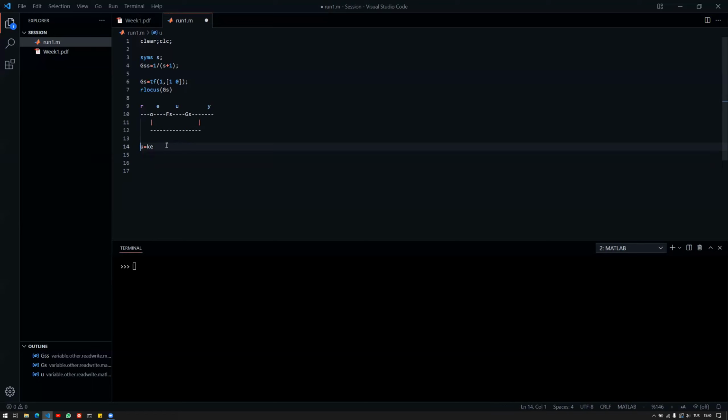Now, if we have such a feedback structure, then I need to work out what the closed loop transfer function looks like, because before I used a controller, I had just the system, the plant on its own. And this plant has a certain characteristic or behavior to it. But now I want to change that behavior in some sense so that I achieve my goal. This means that if I use a controller and have a feedback structure like this, the plant is not the system anymore. The system that I'm looking at is the feedback structure. So what is the transfer function of the closed loop shown here?